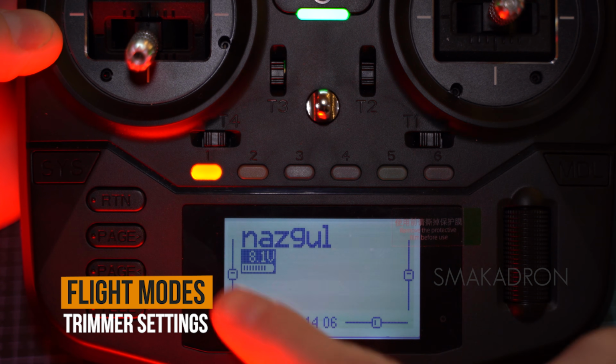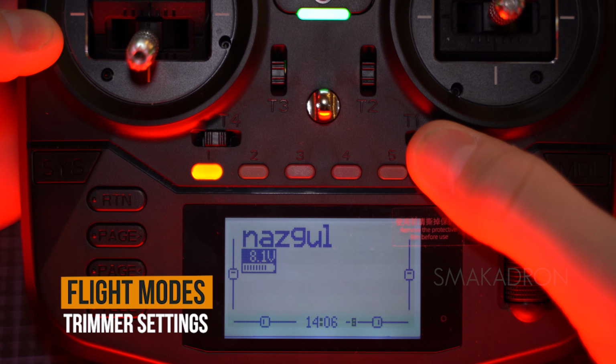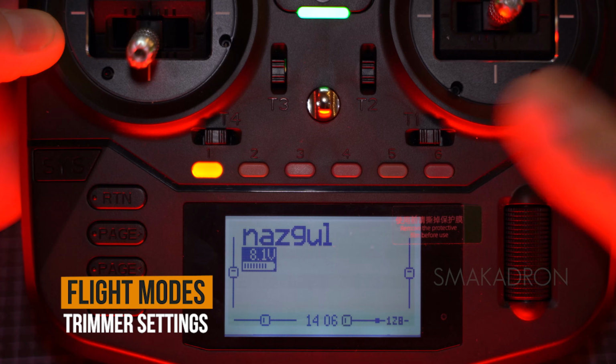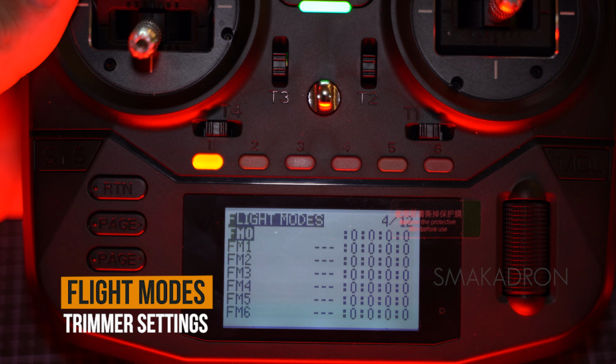In the context of FPV drones and pilots who fly with goggles, working with trims is, to put it mildly, quite a quest, and we set these flight modes using switches, not trims. This is more useful for airplanes. Let me tell you a bit about what might be interesting here for a drone. For example, I have completely removed the trims because sometimes you accidentally move them back and forth and then wonder why the drone is pulling to one side. Most pilots disable them entirely.